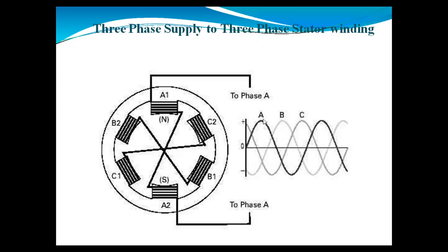Here I am using the letters A, B, C. A is nothing but here we can use the red wire. Here you can use at B yellow and at C you can use blue. It means when we are supposed to give three-phase supply in the three-phase induction motor, at that time we can use the phase sequence that will be RYB.